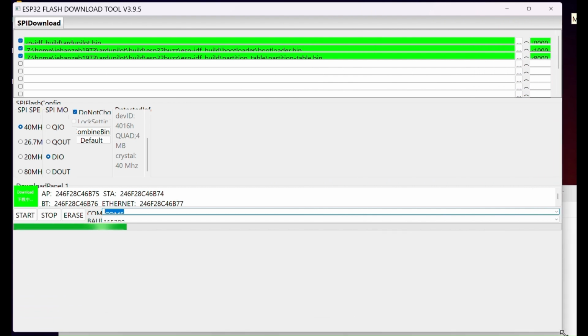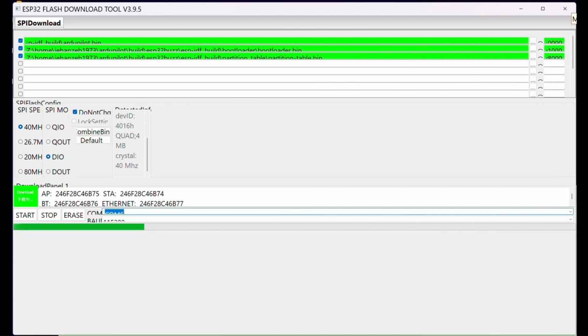So here it's slightly different because even though it's Ardupilot, it's not built and compiled under the Arduino platform. It's a separate WAF environment, and the files generated are also not exactly under Arduino. You will not generate a single bin file. Here you have a bin file, a partition table, and a bootloader bin file. So it takes a little while to upload, but it will go through.